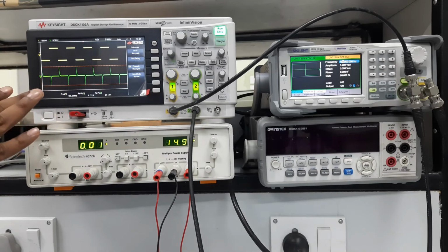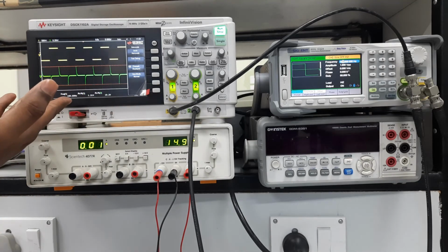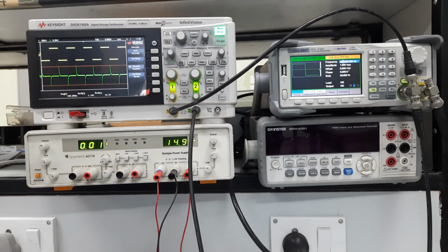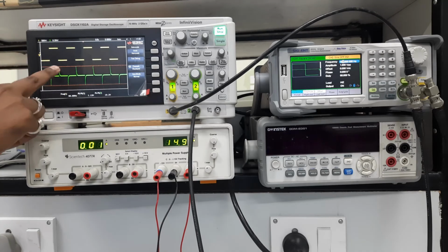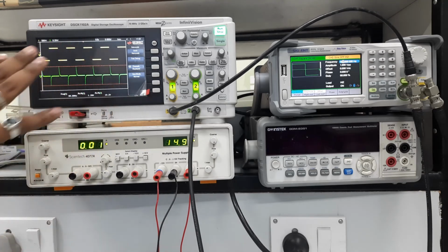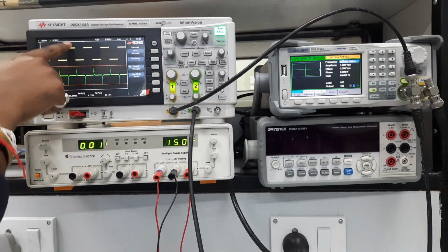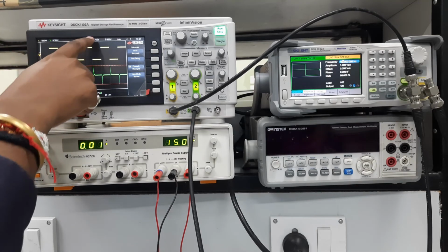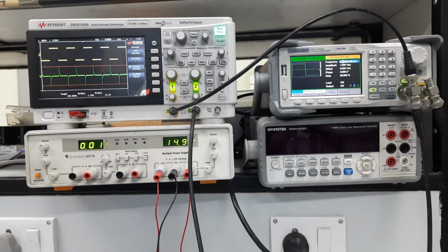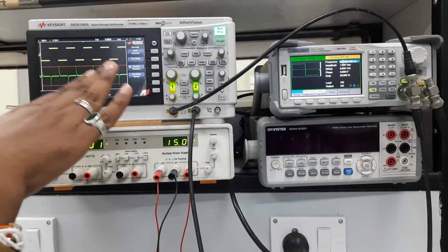So we are getting some spike type signal at the output. Because the differentiation of a constant is almost 0, in both cases we should ideally get a straight line, but there is some small finite transition time from high to low or low to high. That is why we are getting spike type signals in the case of the square wave.